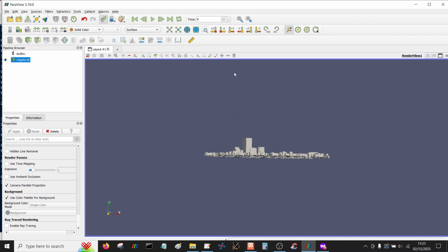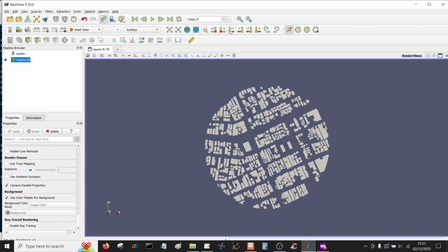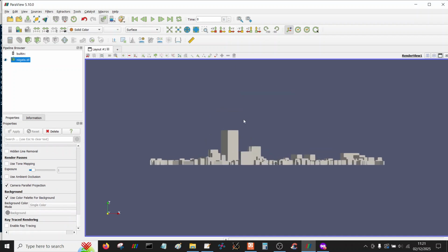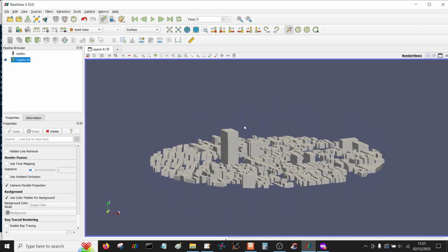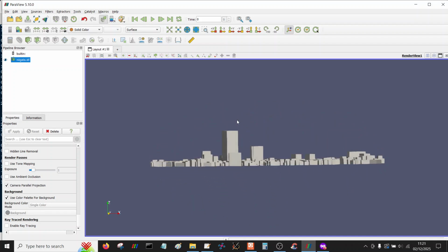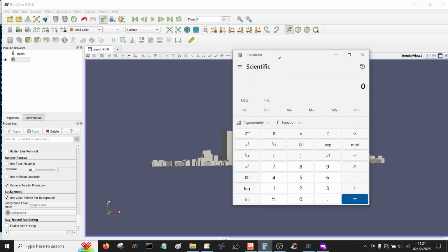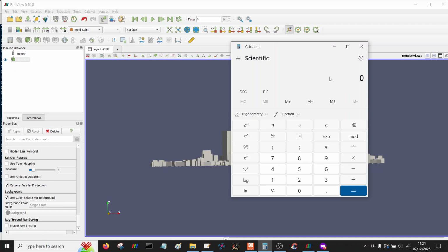Switch the perspective off. So the domain size for this is, when I've been solving it in the lattice Boltzmann solver, I've been doing 600 by 500 by 60, which is a uniform mesh in lattice Boltzmann.